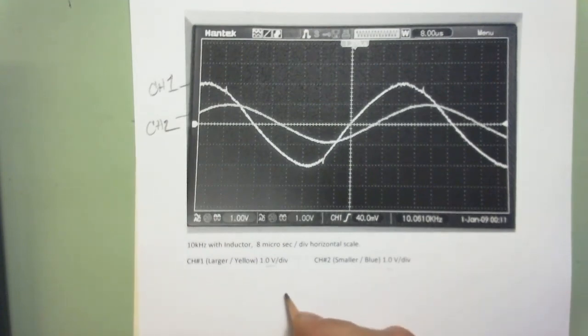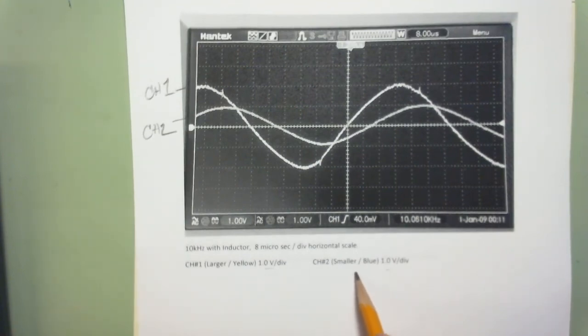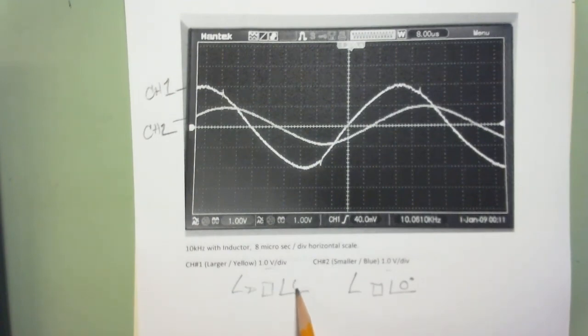The one thing with this one, of course, is that your voltage 2 here, you're going to take this as some magnitude at, I would recommend, your 0 angle, and this one is going to be some magnitude at whatever your theta is, and make sure that that is a positive angle because it's an inductor.